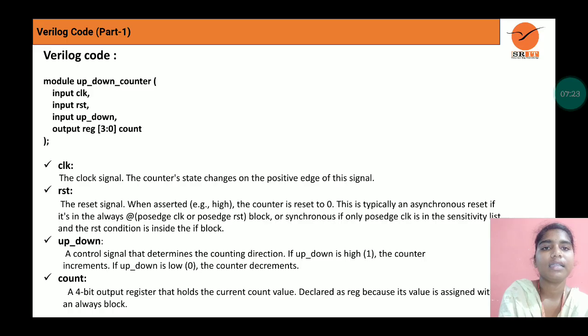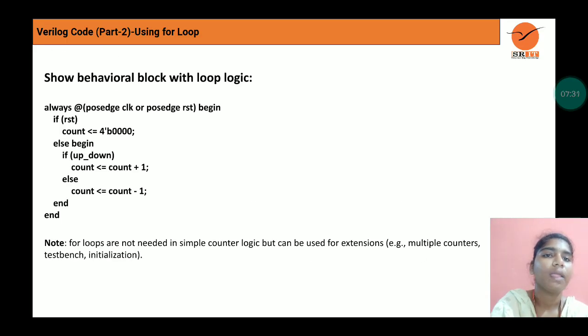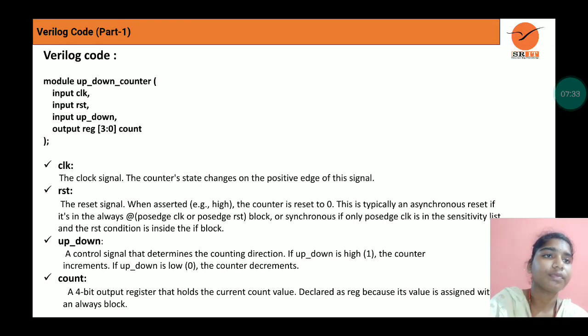Reset: when the reset signal is asserted, the counter is reset to 0. This is typically asynchronous if it's in the always @ block, or synchronous if only posedge clock is in the sensitivity list and the reset condition is inside the block.